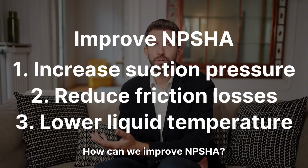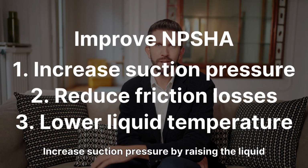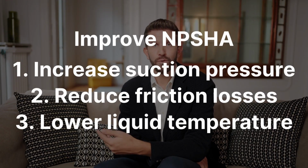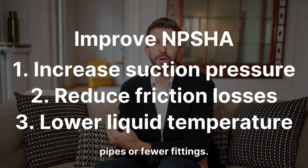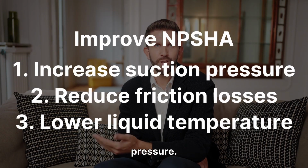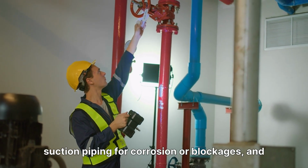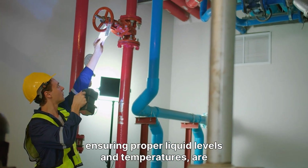How can we improve NPSHA? Several strategies exist. 1. Increase suction pressure by raising the liquid level in the tank. 2. Reduce friction losses by using larger diameter pipes or fewer fittings. 3. Lower the liquid temperature to decrease vapor pressure. 4. Use a booster pump. For plant maintenance professionals, regular inspection of suction piping for corrosion or blockages and ensuring proper liquid levels and temperatures